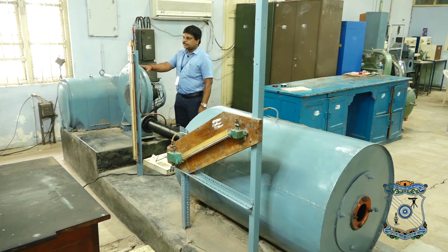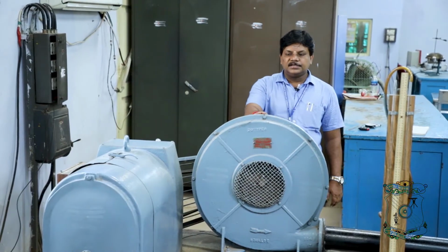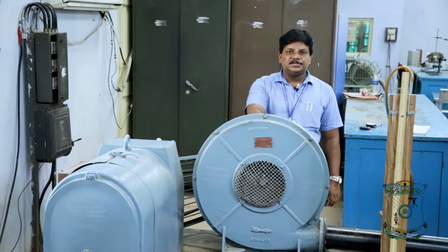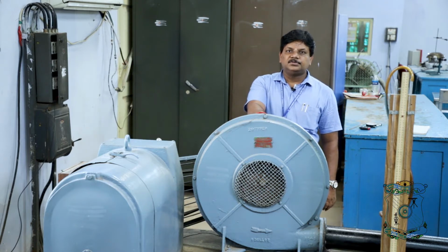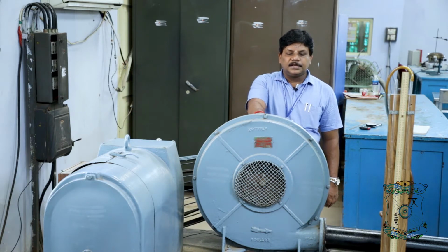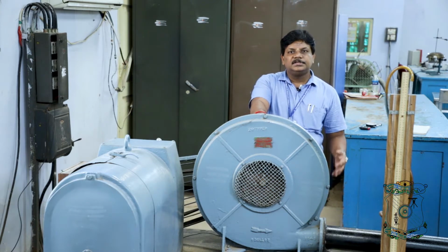Now you are going to change the speed initially. Here is the rated speed of this blower. If you want to know the specifications of this blower, it is a forward curve blower, and the density is given here in the specification, and the discharge, how much air is discharged, is also given in the specifications. So now you are going to change the speed. What is the rated speed? Here you can change the speed from 1750 to 3750 rpm. And also you have to measure the energy meter.